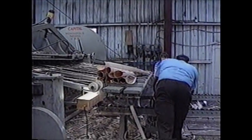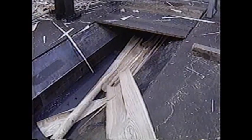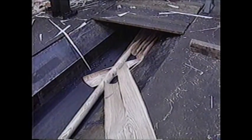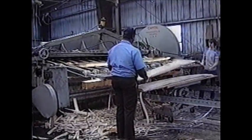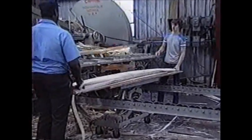Since the flitch's outer face is not parallel to the lathe knife initially, the early veneer is not the full length or full width of the flitch. The smaller pieces are discarded. When the flitch has been trued up, the veneer comes off in full-size pieces.